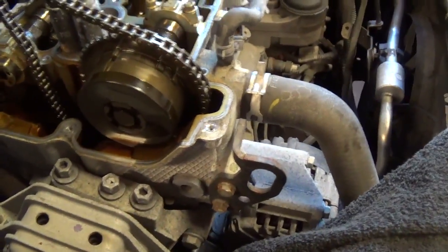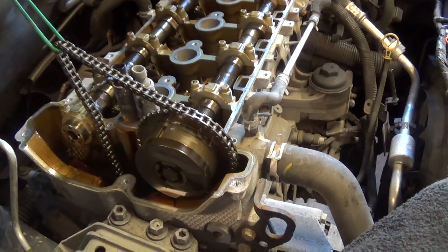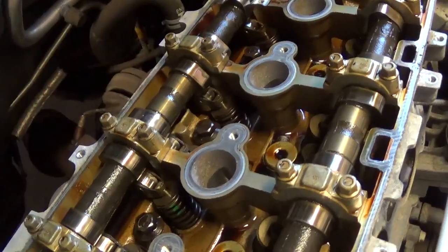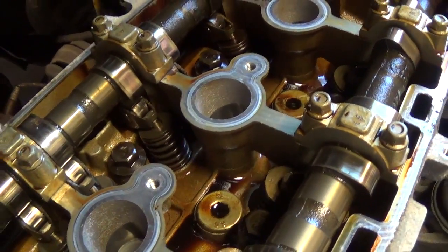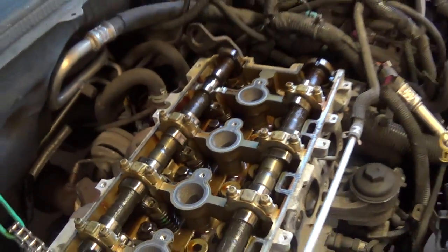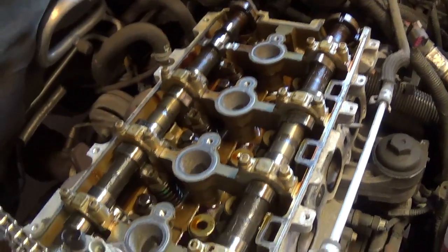So now we're basically home free. We gotta remove both camshafts. I'll leave this sprocket on since now we have plenty of room in that cam chain. And that's all there is to it. Once I take the camshafts off, I just want to eliminate the possibility of a lifter that's stuck or a spring that's broken on these exhaust valves in number 3. We'll just redo our leak down test and off with the head.